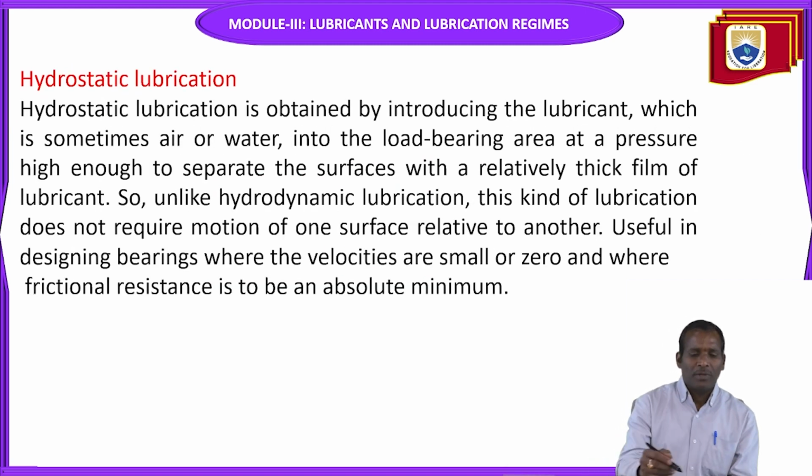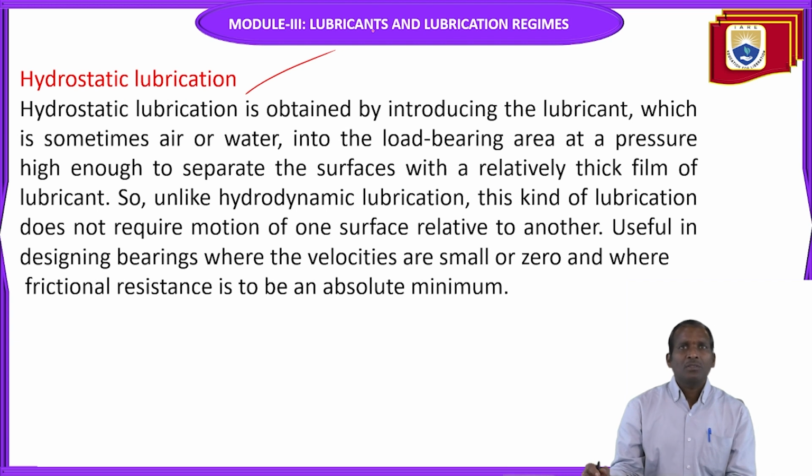Next, hydrostatic lubrication. In this lubrication, it is obtained by introducing the lubricant, which is sometimes air or water, into the load bearing area at a pressure high enough to separate the surfaces with a relatively thick film of lubricant.